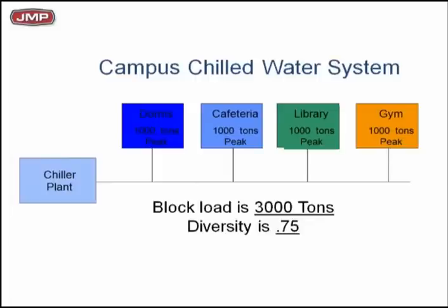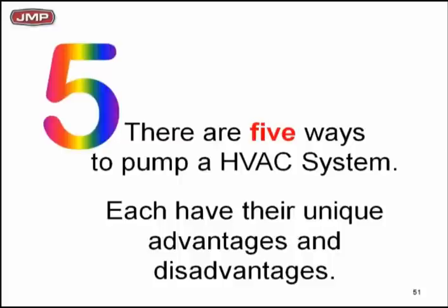If you've got chilled water delta T syndrome, you can't move it around properly. You've got to have that delta T to make it work. Primary-secondary gives you building blocks to work with. This is why it has become so important. So if we summarize all this, and we hit you with a lot, I think it's important you understand that you cannot design a building today without primary-secondary in some form or fashion.